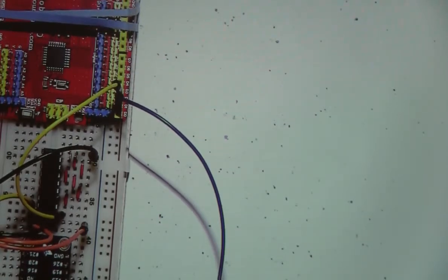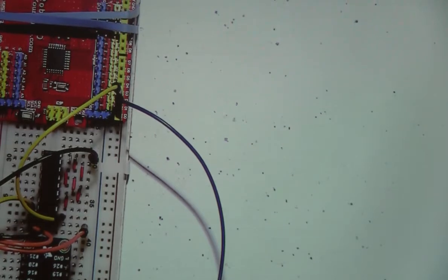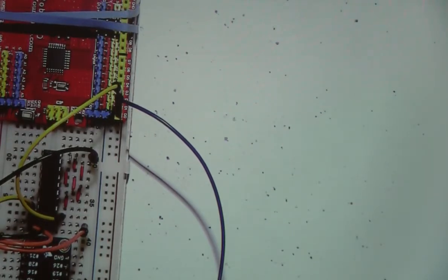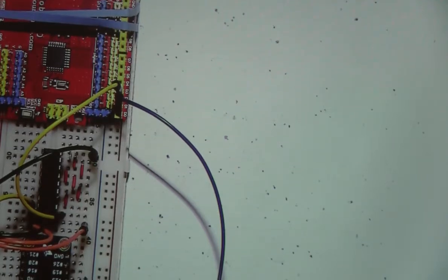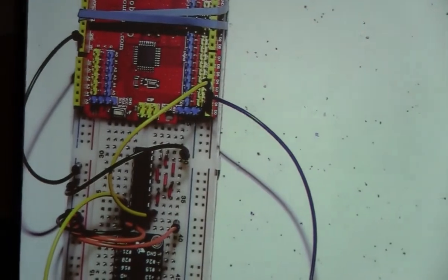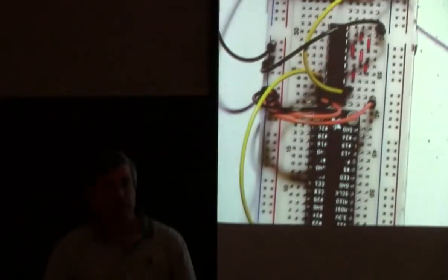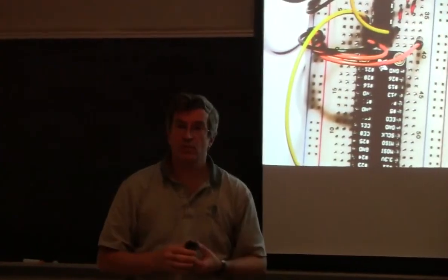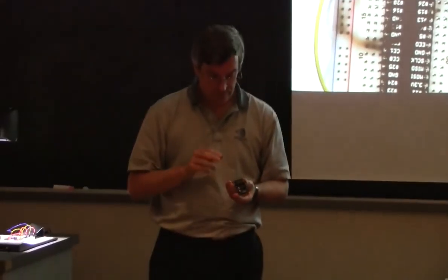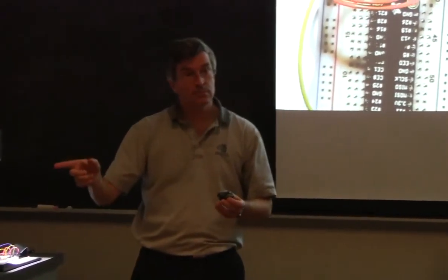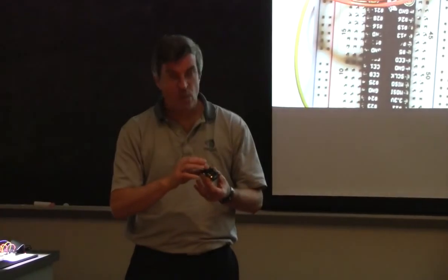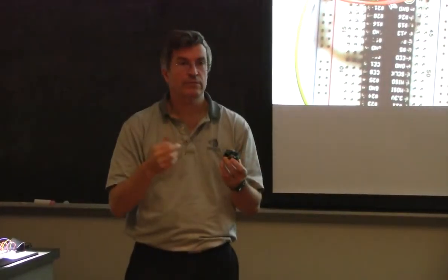There's a hat that I built for the Pi that also has the RS-485. So the RS-485 hooks up to the UART on the Pi to transmit and receive. And then I run software serial on the ATtiny84. And I use my MOS message over software serial to send. So these guys sit and wait and listen on the RS-485.